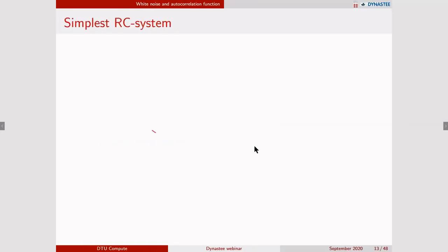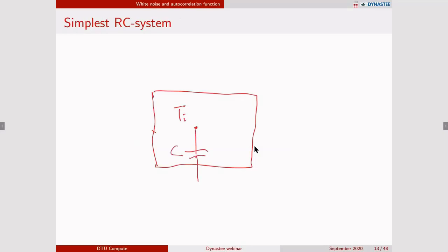So let's take an example. If we make the simplest linear system, kind of a very simple building, we have the internal temperature. Let's think of the internal temperature, and we have some envelope here, and there's some thermal capacity, so some capacity in this building, and we say that this envelope has a resistance to the external temperature, and the external temperature is driving the system, so it's actually like a voltage. So this is an RC diagram, so it's equivalent to voltages and current.